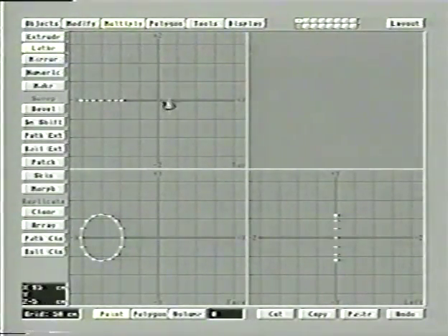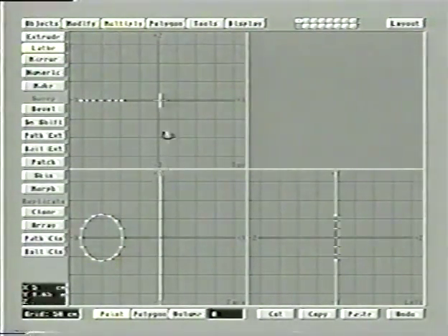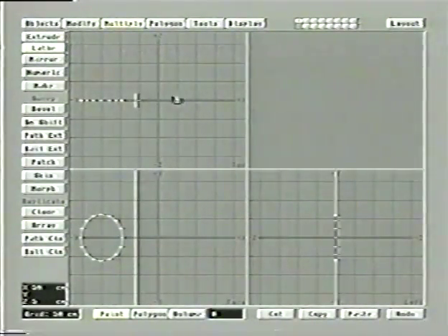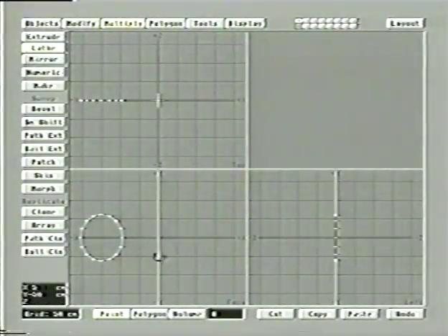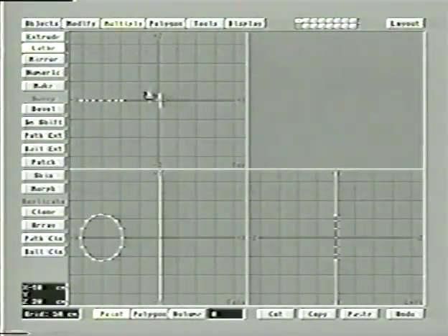And then it's almost like we're running a pole along the side. So we don't click here. We click above the flat object. Now we can drag the pole closer or further. And you see I'm dragging it in the top view, but actually where I'm watching is down here in the face view. Now, this is the pole around which it's going to sweep the object.